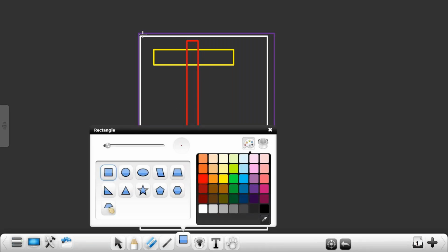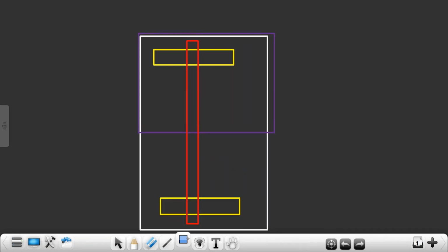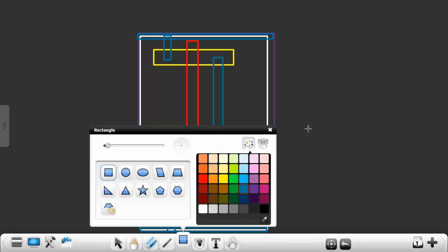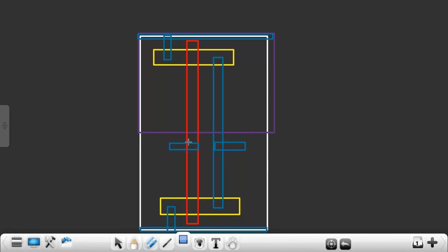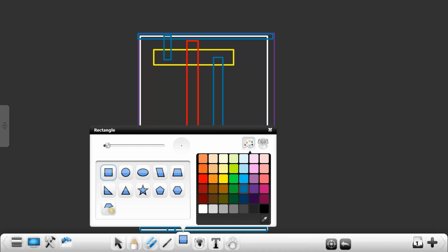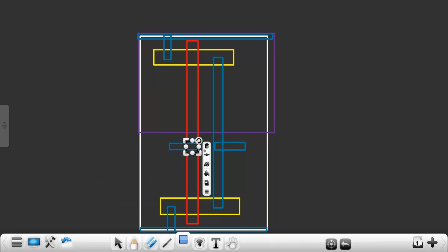And here you have VDD on top, and at the bottom you have VSS. So one side of the P diffusion connects to VDD. One side of the N diffusion connects to VSS. Drain and drain you short. For making the connection, you short your gate, and the gate you connect to one metal layer, right? This is going to give a contact cut. This is a contact cut. So here, one contact cut.